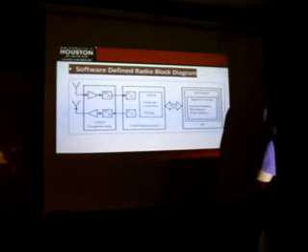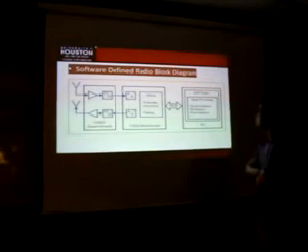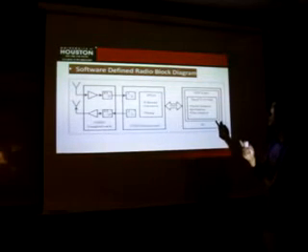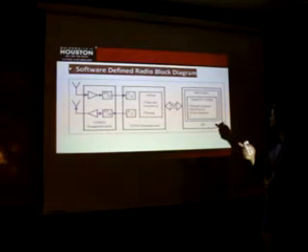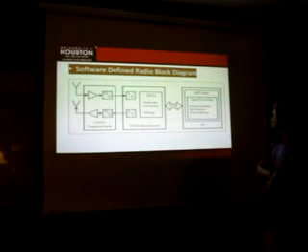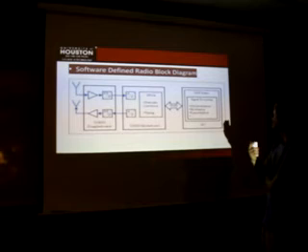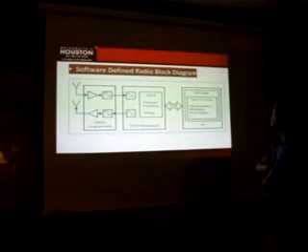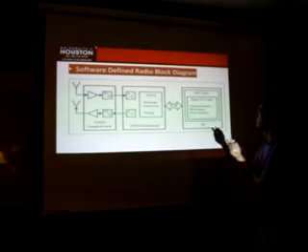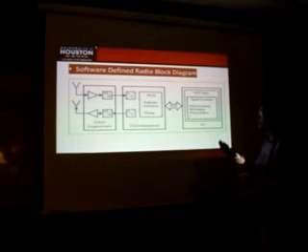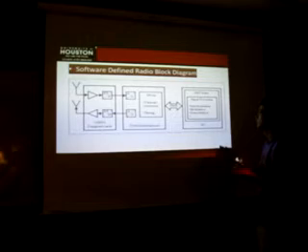So this is the block diagram of the software-defined radio. In the receive path, the antenna receives the signal in the air, and in the daughter board, it converts the radio frequency signal to the intermediate frequency signal. Then the signal is transmitted to the USRP2 motherboard. On the motherboard, the signal is sampled from analog signal to digital signal and transmitted to the FPGA.